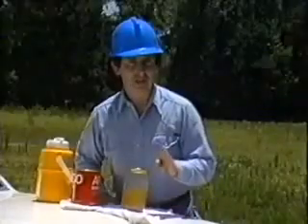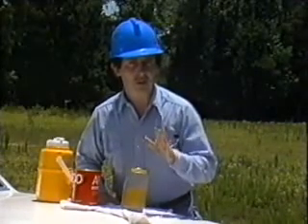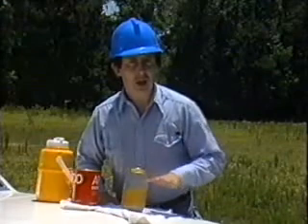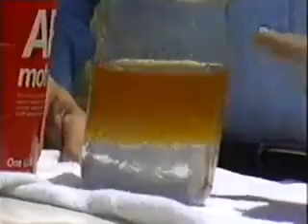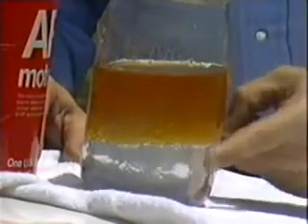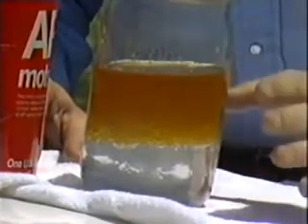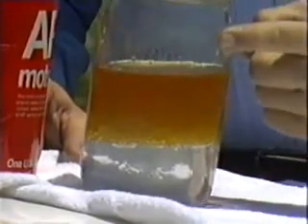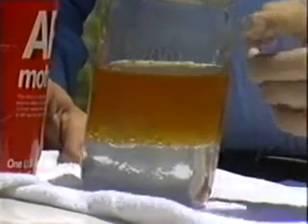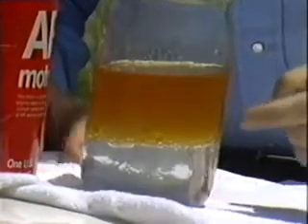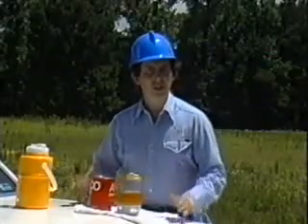Now watch carefully. Because of the different weights or densities of the three fluids, the force of gravity causes them to separate into three layers. The heaviest, water, sinks to the bottom of the jar. The gas, in our model air, being the lightest, rises to the top. Finally, the oil, heavier than air and lighter than water, collects in the middle. This is the basic principle in production separators.